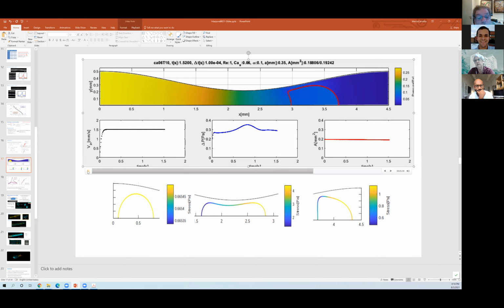And in this case it was pretty good. I think we lost less than 0.5% of the mass. Depending on the discretization, both in space and time, I can make the capsule disappear with time, because it's losing so much mass that it goes away, because the simulation is very inaccurate. So we need to control the discretization to be able to conserve mass.